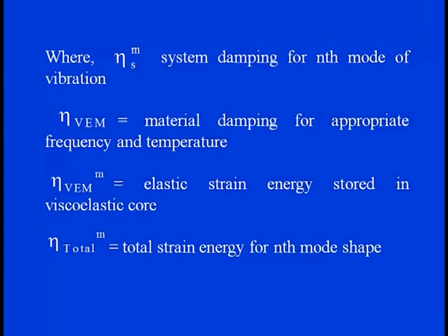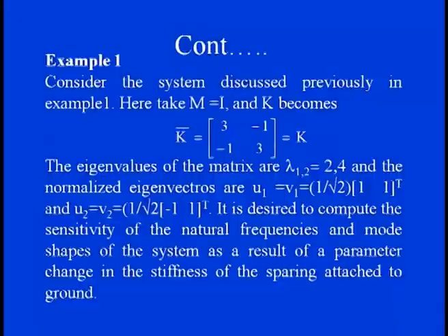So, we can straightaway relate the system damping with respect to the material damping at a certain temperature and frequency, the elastic strain energy of the viscoelastic core, and the total strain energy for the nth mode.